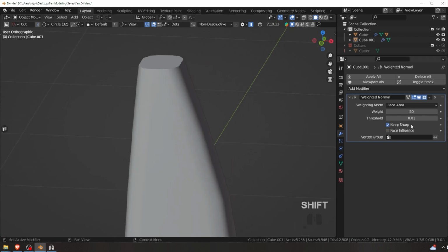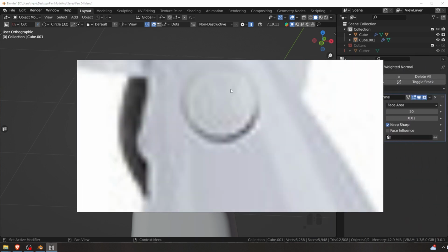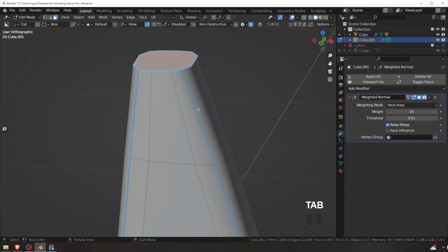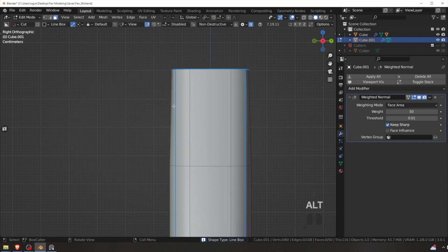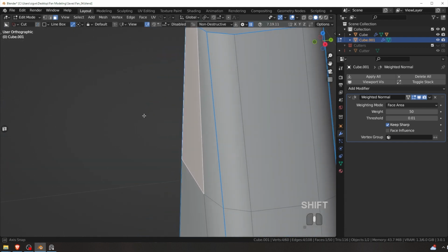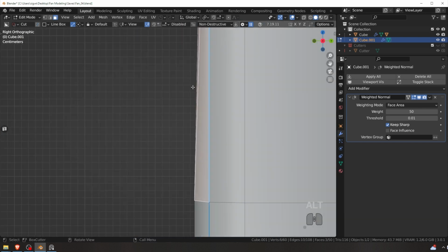Okay, so make sure that you have weighted normals and just delete the bevel modifier. You don't need it for now. And okay, so now we're going to cut this hole right here. But again, you see there is bevel. It starts beveling on this side right here. So this area, it turns this way. So it's a little bit more complicated cut. It's not just a cut on a straight surface. We are going to not cut only in here, and this surface is straight. We are going to also cut in these parts, and they are curved.